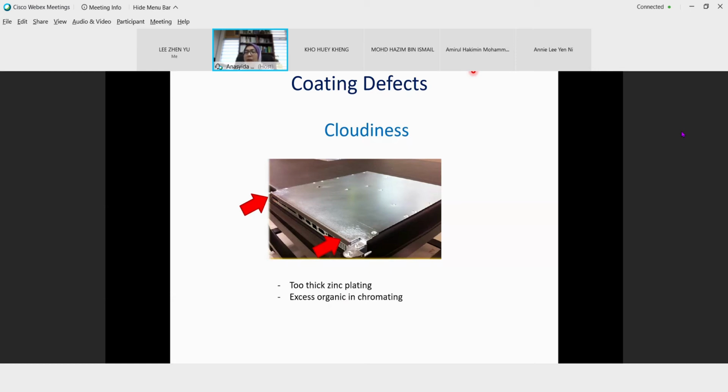But if, for example, when you do failure analysis and you remove the coating, you see there is a dent, a dent under the pinhole. Okay, if you remove that pinhole and you find that it has a dent on the bottom of the pinhole, so this might be due to incoming material. Right? Maybe the incoming material has a problem. So how do we say that it is an incoming problem?